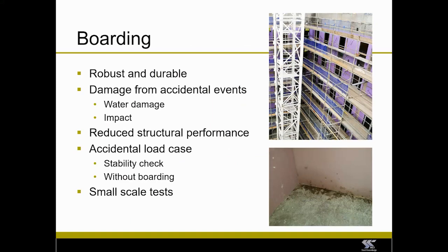So the actual use of boarding is quite interesting, and we get lots of questions about that. Obviously, where we're using steel stability systems, that's generally accepted, but questions arise about the robustness and durability of boards subjected to loads throughout the life of the building. And obviously wind loads blow in different directions, so you have loading and unloading cycles on this boarding, and how that is all taken into account in the design methodology.